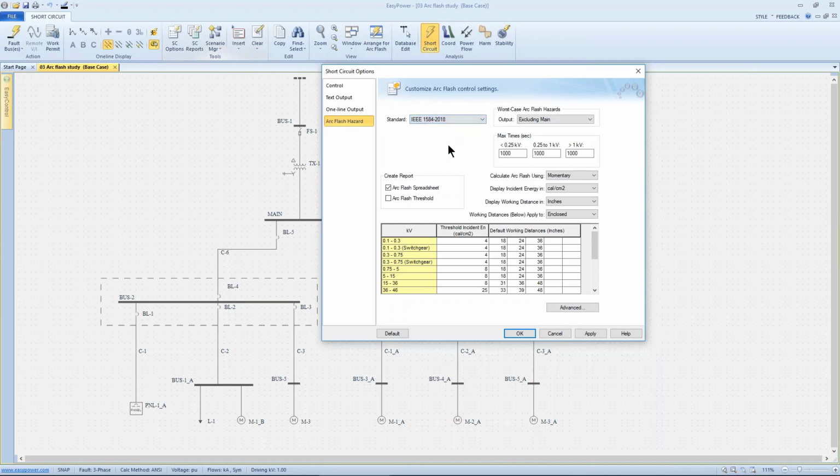Whereas with 2018, it's recognized that some longer trip times may see decreasing arcing fault current and decreasing bolted fault current as well. This can be accommodated, because if I've selected the integrated method, the current used for the first cycle is the half cycle current. If the fault lasts longer than a cycle, then for the next 8 cycles, the tool uses the interrupting current, or the 5 cycle current.